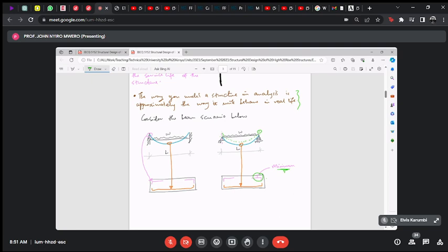it will start making sense. This is similar. No, let me pause it at that point. But when you talk about steel structures and you talk about continuous construction and simple construction, it's the same thought. If you assume it's continuous, it will send moments to the supports, which you'll need to then design for. If you assume it's simply supported, it will not send moments to the supports, but it will send moments to the span. So you'll have a bigger moment there.